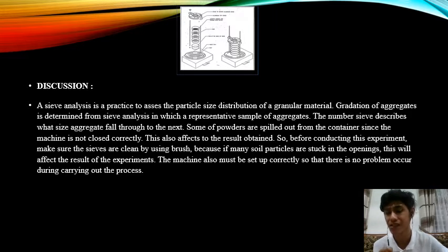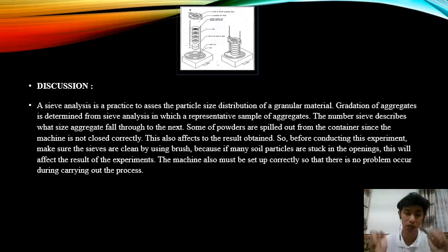So before conducting this experiment, make sure the sieves are cleaned using a brush because many soil particles get stuck in the openings. This will affect the result of the experiment. The machine also must be set up correctly so that no problem occurs while carrying out the process.